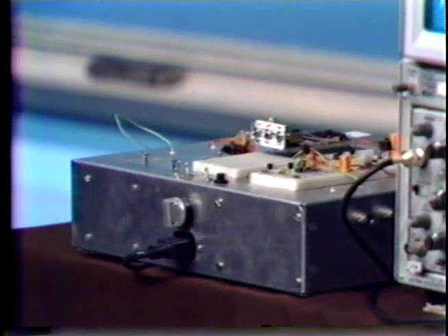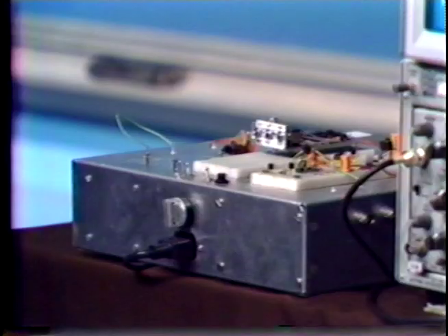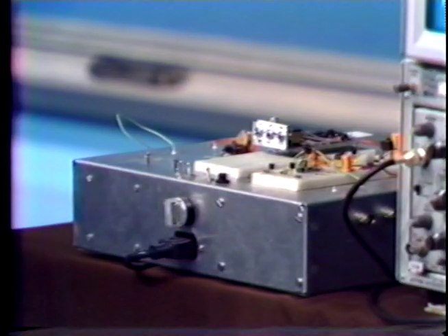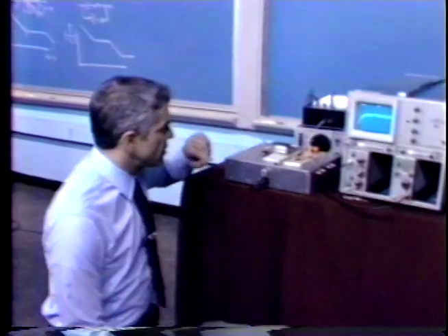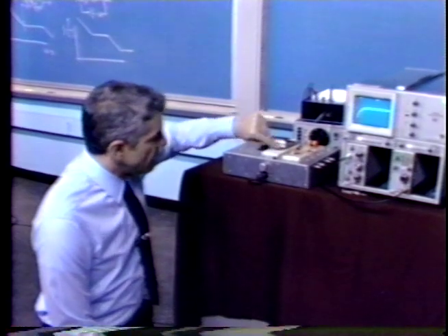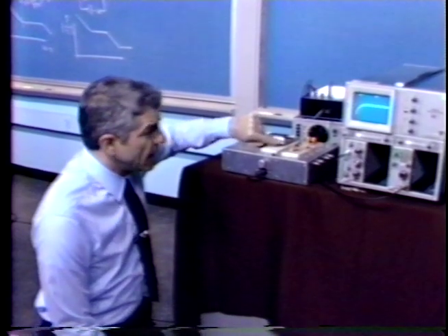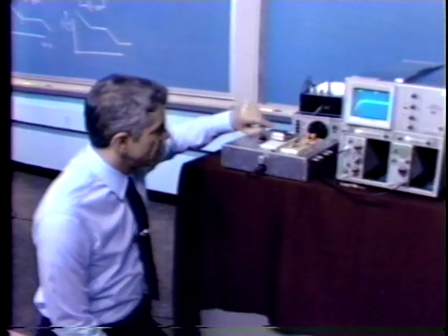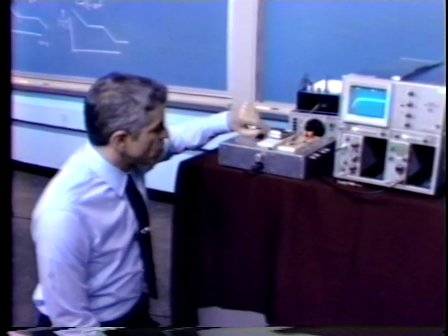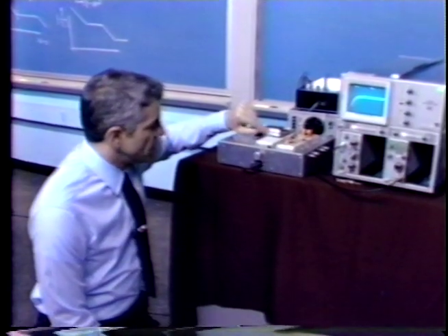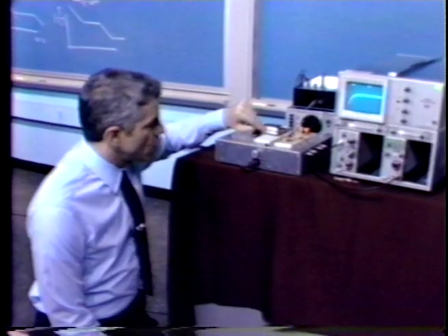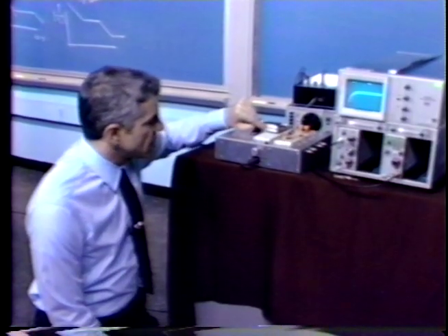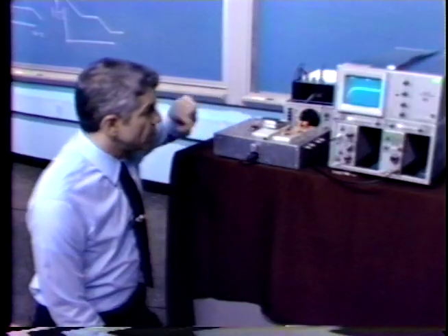And what I'd like to initially look at is the behavior of the system when we have a single pole roll-off associated with the amplifier. And we get that by having the right-hand switch in the upward position. And we now have removed the additional pole in the loop. The R is quite small and the C is an open circuit. So we've now removed the additional pole.